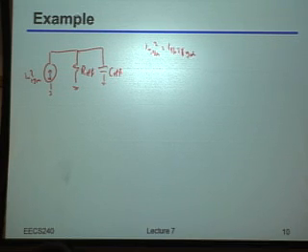So what's our output impedance as a function of frequency in the Laplace domain? You can just use R effective and C effective. Yeah, it's just R effective over 1 plus S R effective C effective.